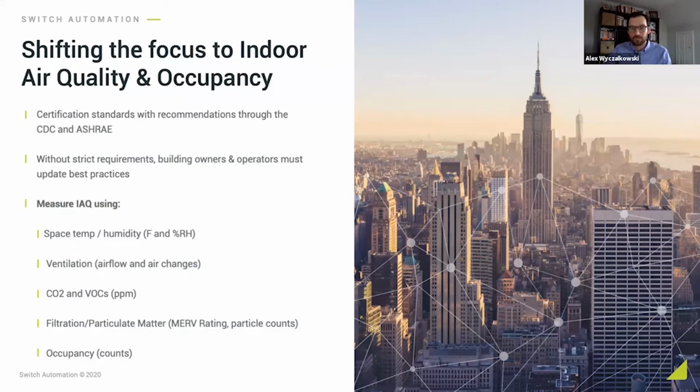So we're taking these guidelines, comparing them to the data that we have, and determining whether our indoor air quality is good. If it's not good, if it's bad, then we need to take some measures, do things like increasing ventilation, filtration, humidity. So that's kind of where we're starting. But before we consume all this data, we need to develop a strategy first.